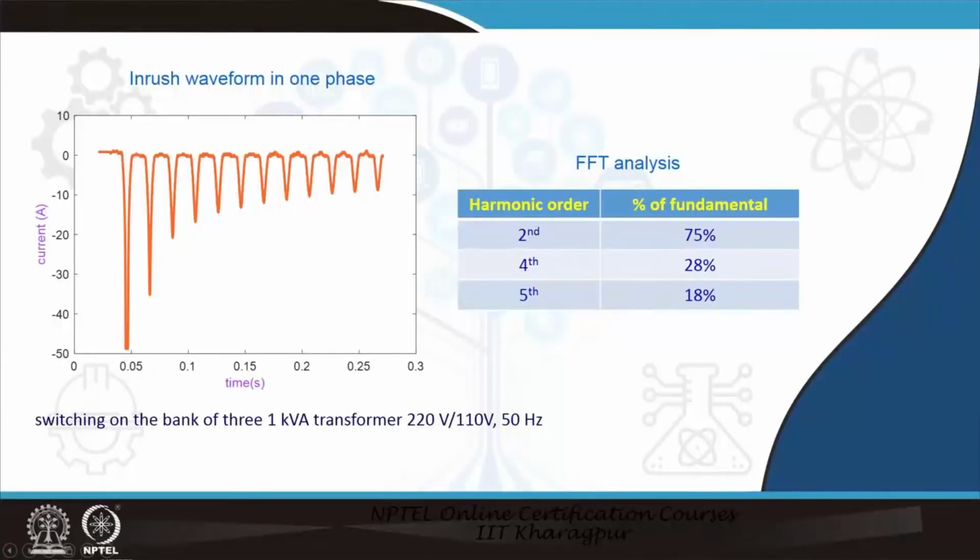This is not a fault situation, and it will unnecessarily trip the relay, which is not desirable. At that time the relay should be blocked so as not to operate the breaker, so that there will be no power interruption from the grid operation perspective.